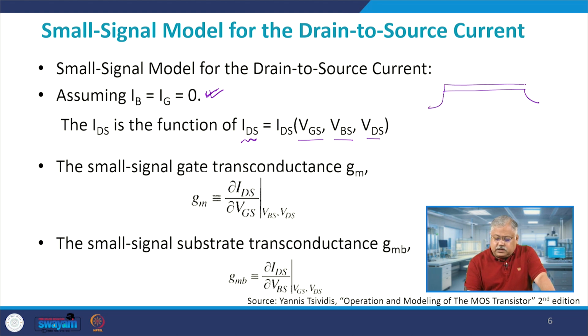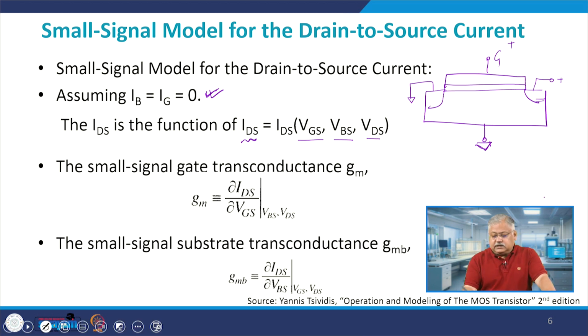So, if I have a MOSFET here, I told you earlier also that generally my source is grounded, I apply a drain bias, I apply a gate bias, and my body is also grounded. So, body and source are grounded, whereas gate and drain are given some potential. However, whenever we write Vg, we do not write Vg, we write Vgs or Vds or Vbs. What does it mean? It means the voltage at gate, drain and bulk with respect to source.